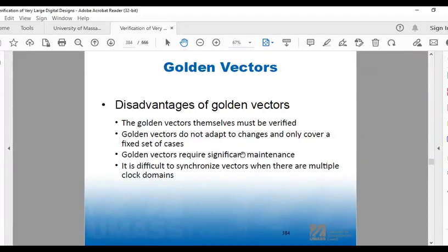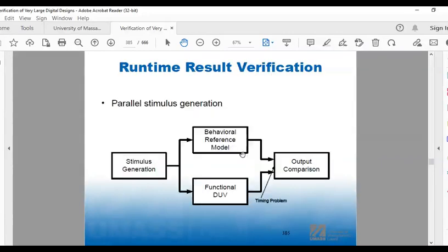And a lot of times it's gathering it and then somehow processing it so it can be test vectors. So there's maintenance, right? I talked about that. You know, people go out in the field, they gather all this data and they come up with terabyte drives, and it has to be cataloged and organized, and inevitably things aren't the way you'd like them to be. And then what I keep saying is you have to synchronize them. Right? The clock domain that you gathered in is probably different from the clock domain in your simulator.